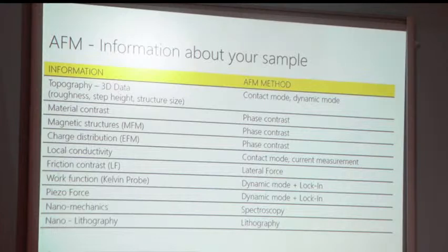From magnetic structure, if your samples are magnetic in nature, you can perform magnetic force microscopy to get the magnetic domains. If your samples are conductive in nature, then you can measure their electrical force, their current, their work function. If your samples are piezoelectric in nature, you can measure their piezoelectricity. At the same time, if you are working on tribology, then you can also measure the friction on the sample. Similarly, for nanomechanics, by applying force onto the sample, you can measure their stiffness, their modulus, their adhesion. All these properties you can also measure.